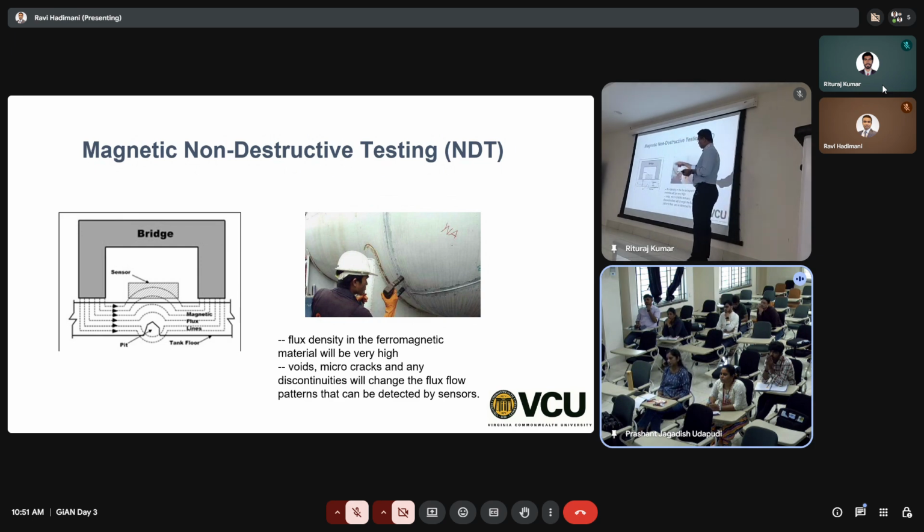And so when the secondary coil reads, depending on what level of cracks and stresses you have in the material, the secondary coil will read a different amount of magnetic field. And that is one way people go through these big pipelines that are used for supplying petrol or gas or whatever it is, or water, to see if there is any microcracks or any damage.